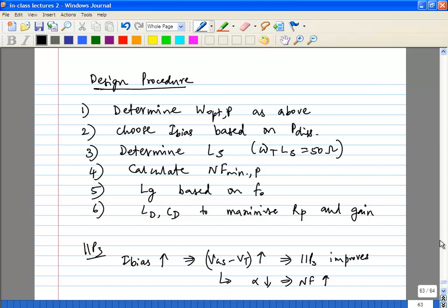But I assumed what he was asking is that because the output swing increases, it could impact linearity, again IIP3, in a second-order way. The swings at the output will never go to volts or something like that. This is not like a power amplifier. Swings will be very, very small. The only thing you could see is the swing affecting your linearity, maybe if the swing gets high enough.